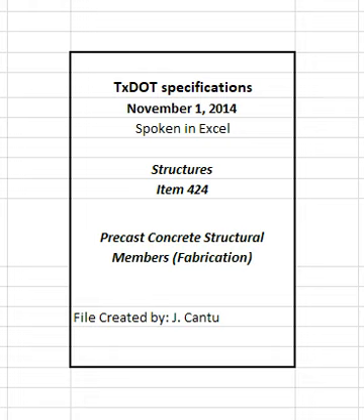Approval of optional designs does not relieve the contractor from the responsibility of furnishing a satisfactory completed structure. Provide submittals for precast post-tensioned members in accordance with this specification and Item 426, post-tensioning. 4.1.1.2 Non-stressed members. Furnish shop drawings for non-stressed members when required by the plans or pertinent items.